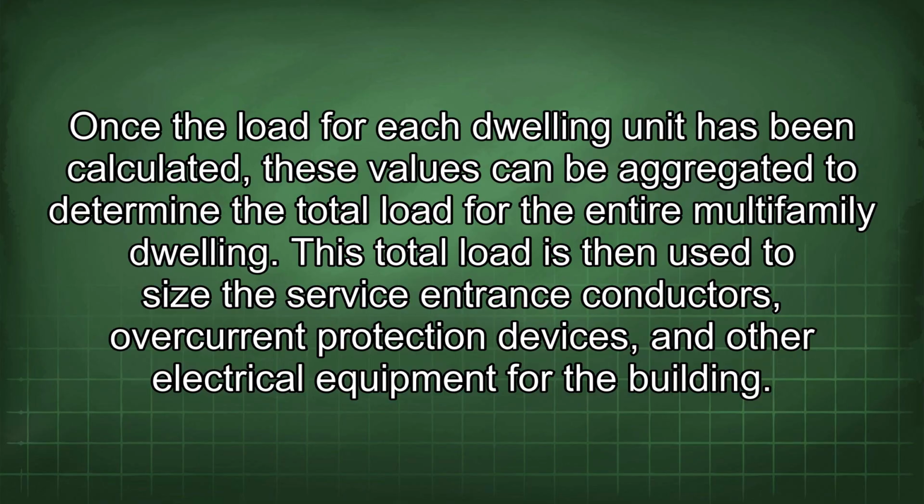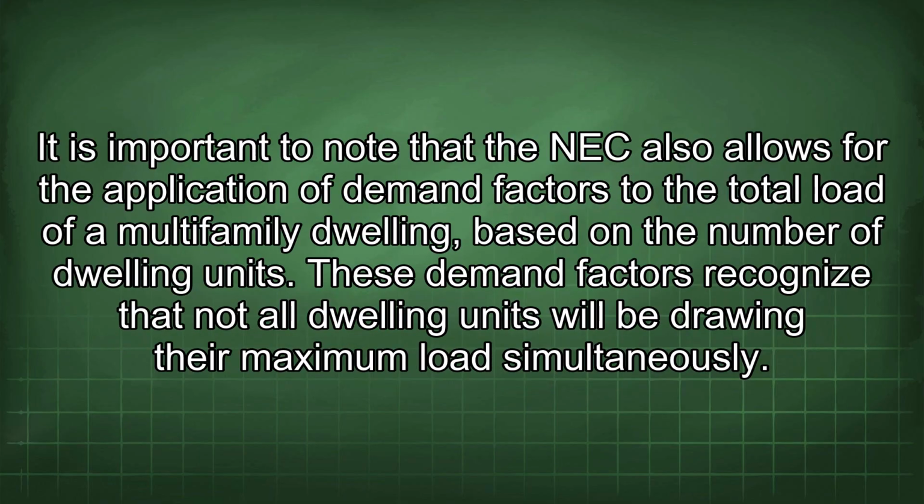This total load is then used to size the service entrance conductors, overcurrent protection devices, and other electrical equipment for the building. It is important to note that the NEC also allows for the application of demand factors to the total load of a multifamily dwelling based on the number of dwelling units. These demand factors recognize that not all dwelling units will be drawing their maximum load simultaneously.